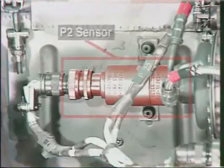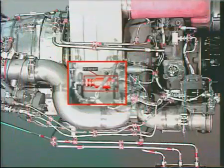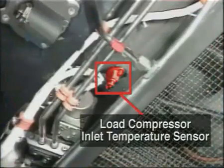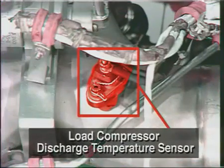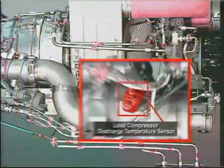The P2 sensor is mounted on the right side of the air inlet plenum at the 3 o'clock position. The load compressor inlet temperature sensor is installed at the 5 o'clock position on the load compressor housing. The load compressor discharge temperature sensor is installed at the 3 o'clock position on the bleed air manifold. The data is used for condition monitoring.